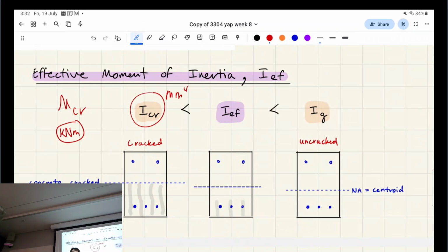the transformed section. Do you remember in solid mechanics there's those beams with timber and steel and you use the modular ratio method? It's the same thing, but we turn the steel into concrete. And then pretend that all the concrete below this line is cracked, or effectively zero area. So we just ignore the concrete below. But it's also a function of dn, this part of the concrete rectangle. So it's like a quadratic relationship between dn and everything below it being cracked. Do you know what I mean? Yeah. Anyway.